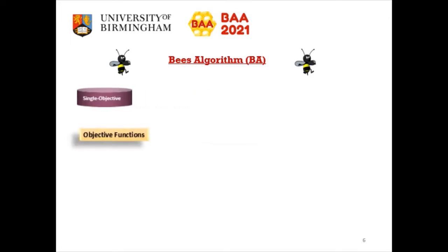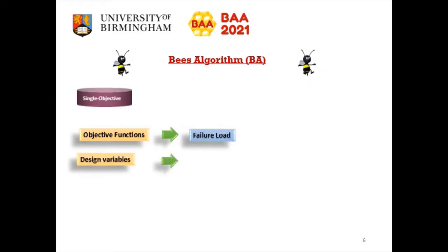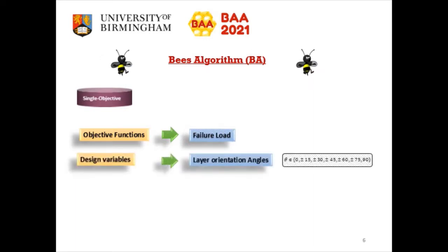In the single objective optimization problem, the optimal layup is determined based on maximizing the interlaminar strength of laminates. In this case, the optimization variable is the stacking sequence.